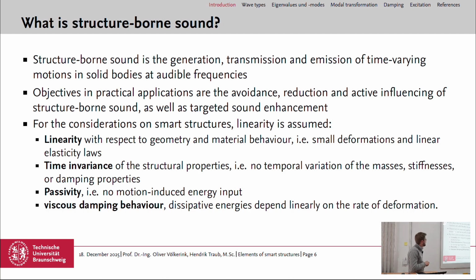And in this course, we have some assumptions: linearity. So we assume that geometry and material behavior is linear. We assume small deformations, linear elasticity laws, time invariance of the structural properties, so they will not change, no motion-induced energy input, and viscous damping behavior.